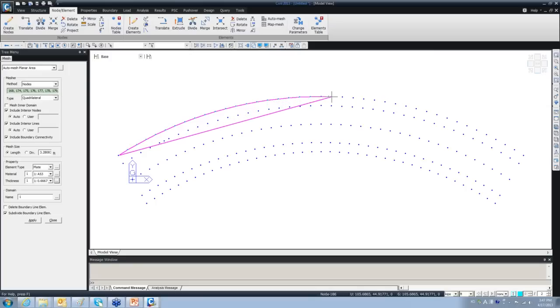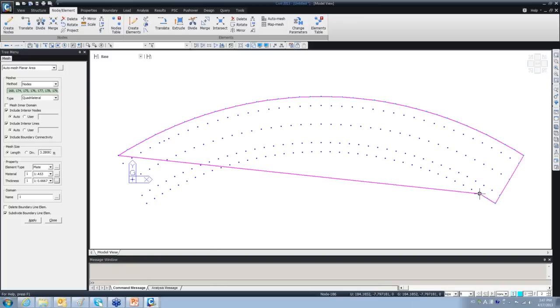So you need just to define an enclosed area for this mesh, and then the software, based on the coordinate of the node and the arrangement that you have, defines the best mesh available for that area. If you want to define the mesh in the inner domain, you can also ask it to do that, but I don't recommend that because it gives you some random shapes that may not be very interesting for you. So you can go just with the general approach.